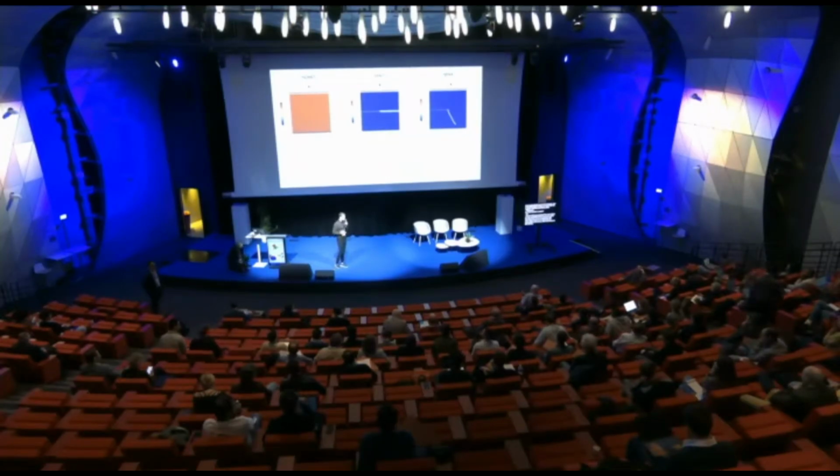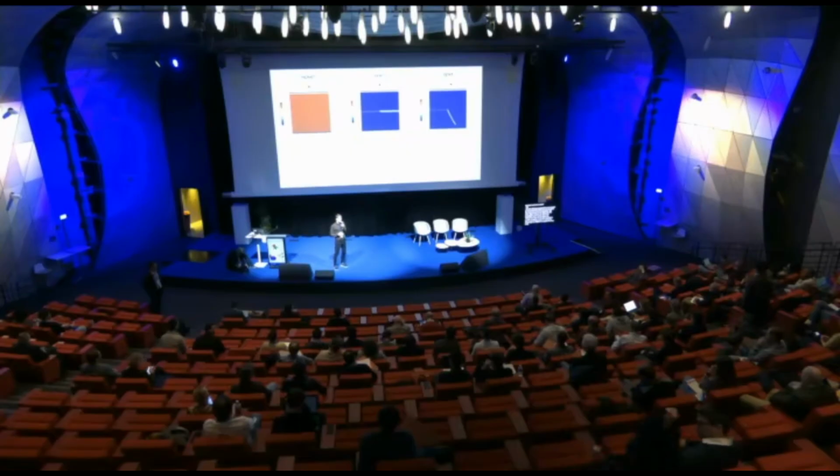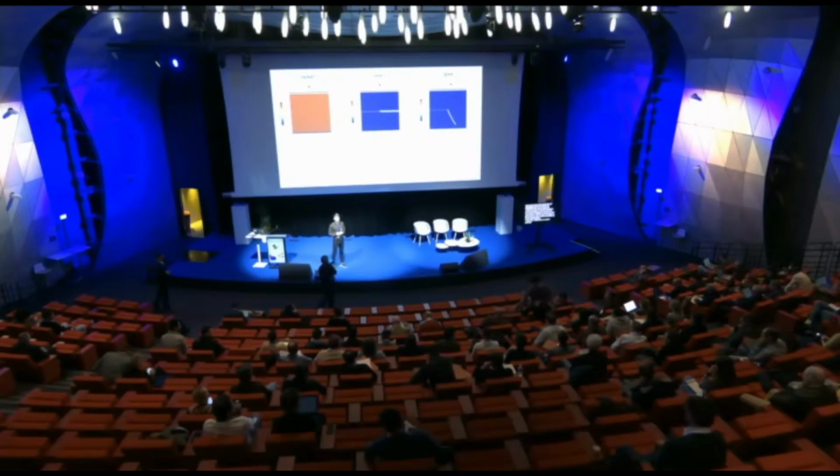Yes, there are many things that we can do. This does not use, for example, MPI parallelism, which would really help this kind of simulation. But this is because these are mostly preliminary results. It's also very common to use adaptive meshing methods, so that you adaptively resolve the mesh as the crack evolves. This is also not something we've implemented yet. But there are many methods that could really speed up these simulations. Yes, thank you very much.